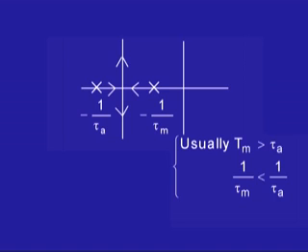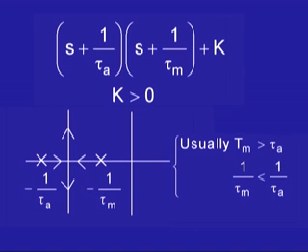Now, if k were 0, then these would be the two poles. The root locus method tells you that when k is not 0 but k is positive, then the roots will not be at these 2 points, but will be somewhere else. And anticipating the root locus method, what we can conclude is that as this coefficient k is increased from 0, the roots move as it were towards each other, or in other words the roots change their values till for some value of k the two roots become coincident.